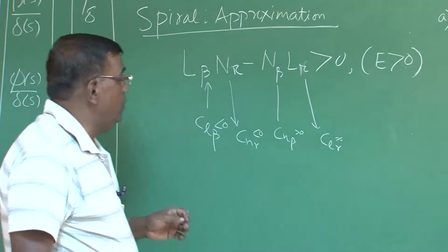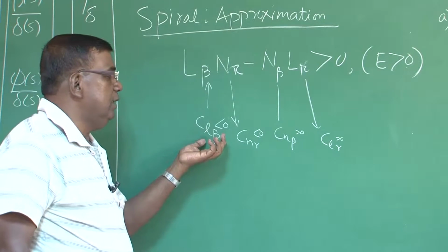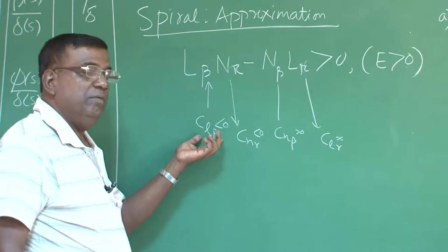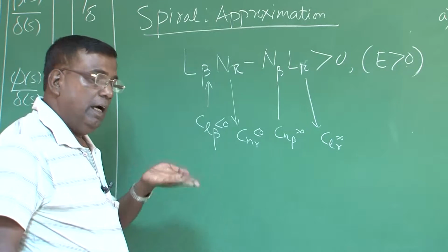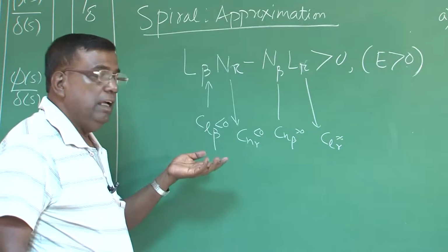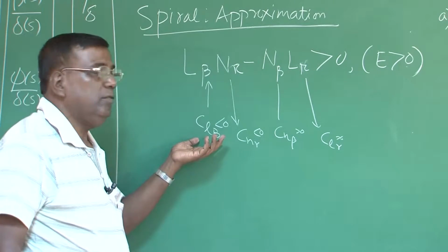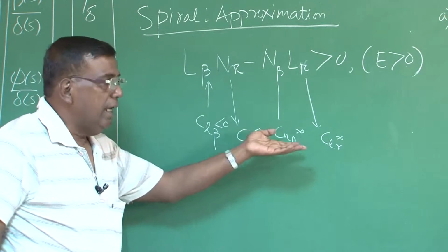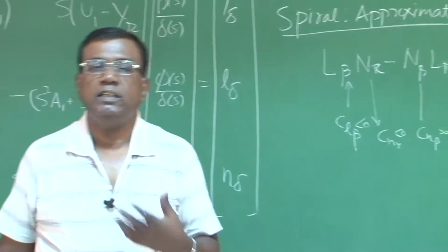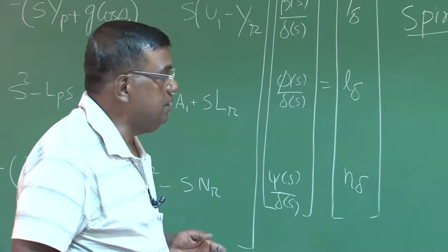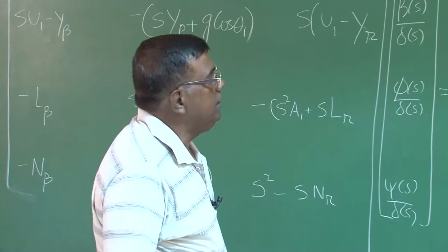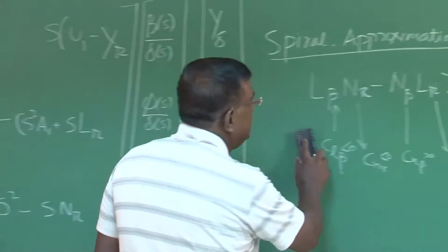So we understand who the non-dimensional derivatives are. They play the role. We also understand how to change the value of CL beta. If I increase vertical tail height, CL beta will increase. If I make it a high wing, CL beta will increase in the negative sense. Like that, as a designer, I should know, if I want to tweak this parameter, which geometric design parameters I should change. So this should be very clear before you go for the spiral approximation.